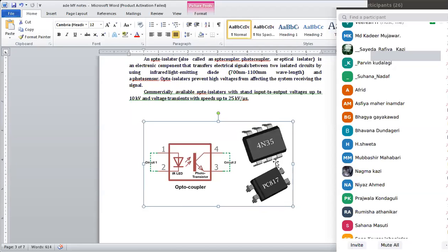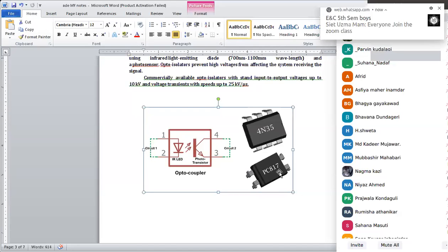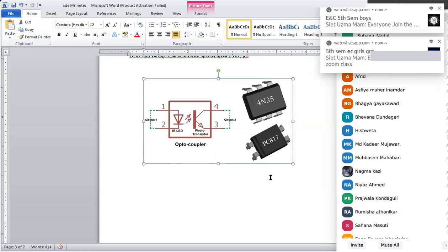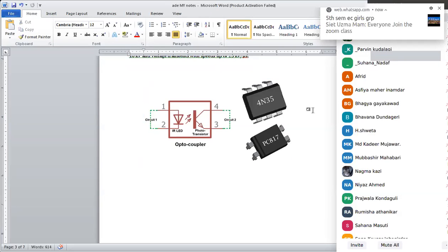Optocoupler? See, on the right side in this figure, you can see one IC is there, no? PC817. Can you see? Yes, sir. This is the IC we saw in the previous class. Actually, I don't have that image right now. So what is happening here? On these two pins, the microcontroller is going to give signals to this PC817 to switch on the motor.